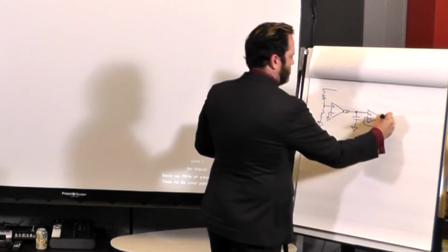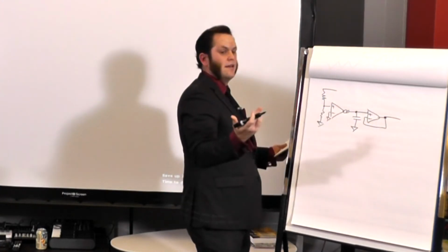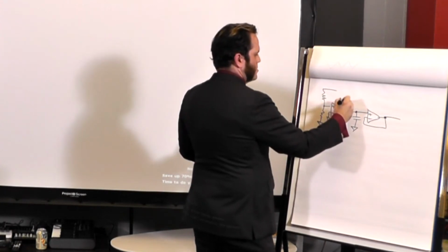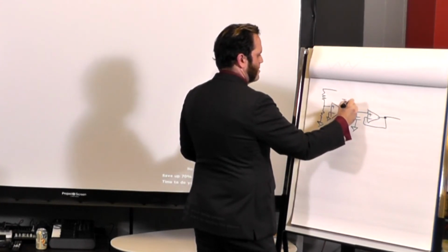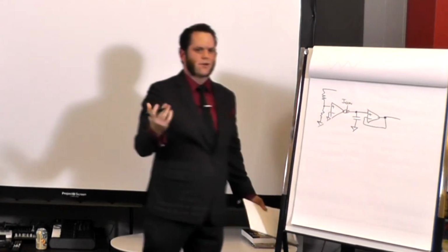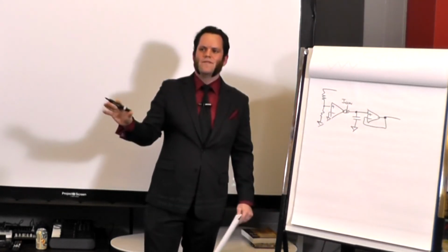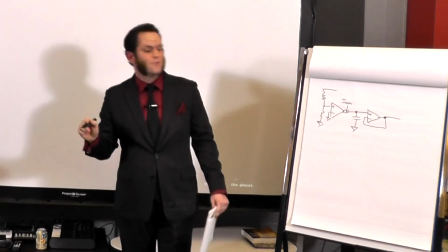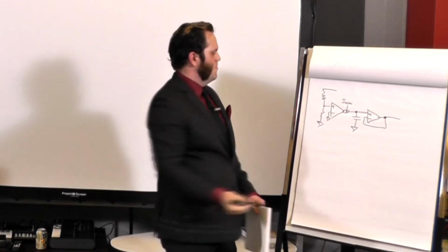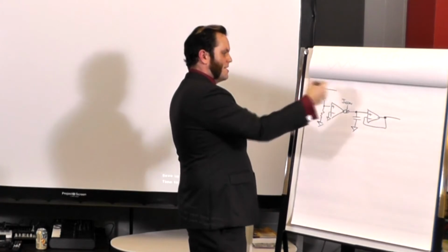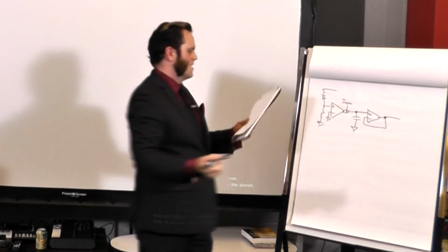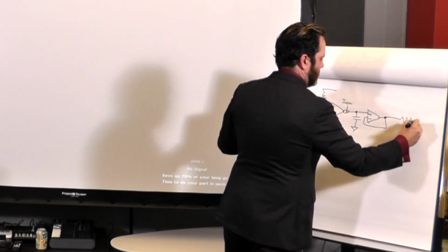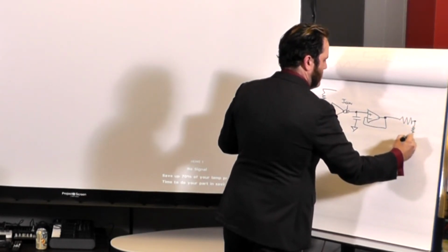And then we're going to throw that into another OTA, because we like using OTAs. They're really neat. By the way, this is where our voltage control comes in. I'm going to label it current control for right now, because OTAs are current controlled. I'm being a little hand wavy about the current control for a moment, but don't worry, I'm going to get back to that magic glue in a little bit. So this essentially is our integrating structure right here. And we're going to then tweak another OTA to be our comparator for us. Throw another one there.